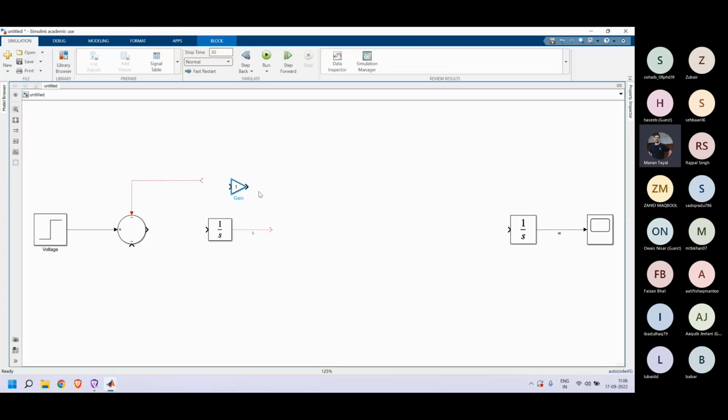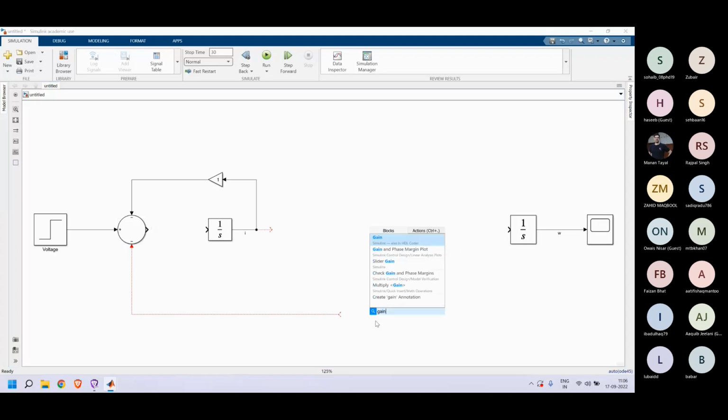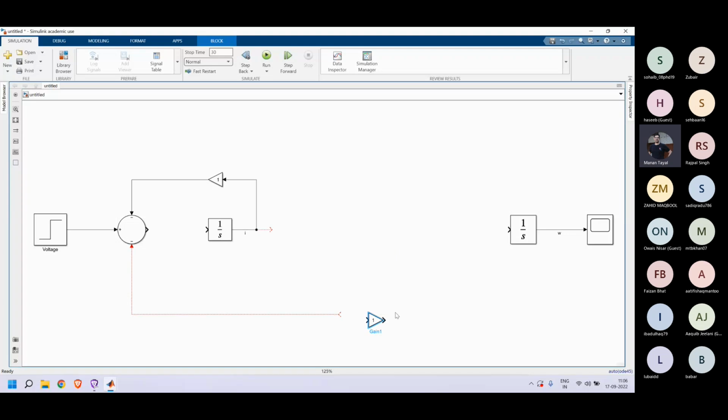If I use Control I, I can flip it. So Control I for flipping it. Okay, and directly add this here, and take this input from the current, which I'm getting from the integrator basically, and again I want a negative contribution from a scaled version of my angular velocity.